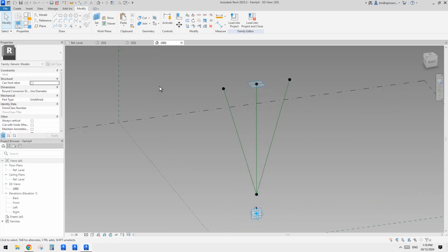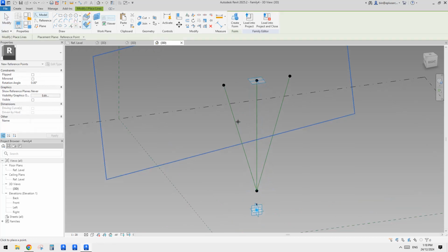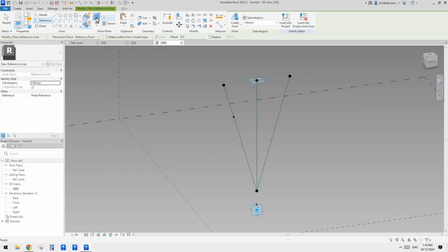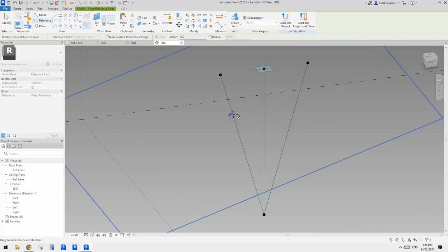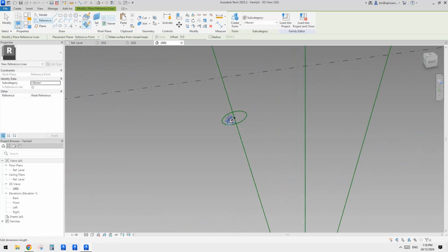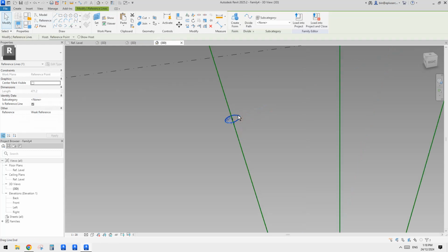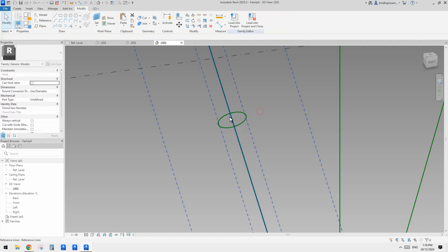So we're not going to make this parametric. So let's just place a point. Use draw on face onto this, and create a circle. Use draw on work plane onto the point. Okay, and the size will be, not sure, like 150 diameter or 150 radius, so 300 diameter.